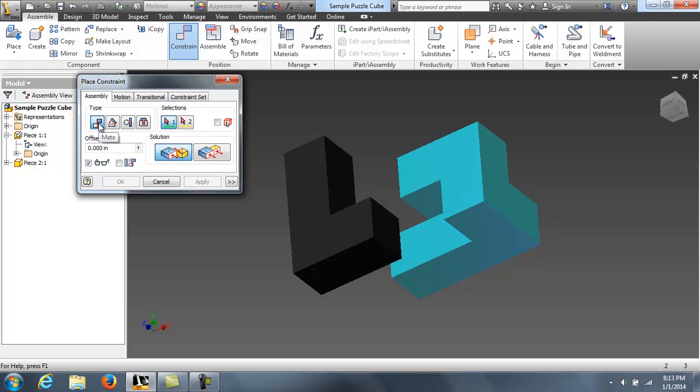And within assembly, we have four types. There's mate, angle, tangent, insert. Mate is already the default one. It's the easiest one. It's when you want two surfaces just to come together face to face or come together flush. Now, we'll do just an example. Angle shows how pieces can come together at set angles, undirected, all sorts. Tangent works best for round objects, cylindrical objects when you touch at one contact point. Insert comes in handy when we insert pegs into openings, screws into screw openings.